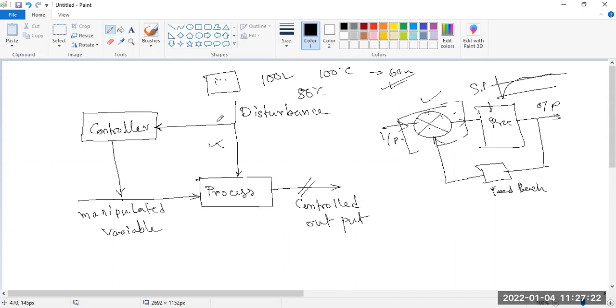We take interest in feed forward control action when the disturbance or the process is changing, because then this control action is very efficient. But whenever we don't have any information or any rule base, then we apply the feedback control system, because we don't know how much steam flow is required for 100 degrees centigrade within this time.